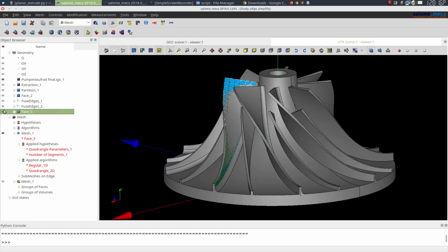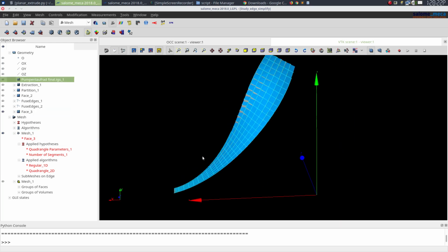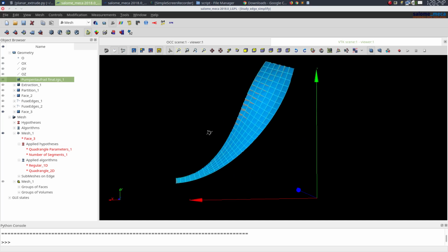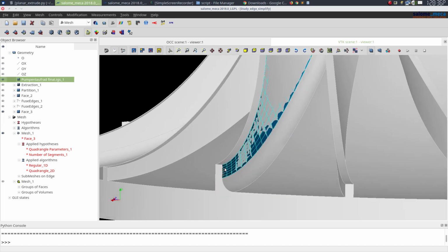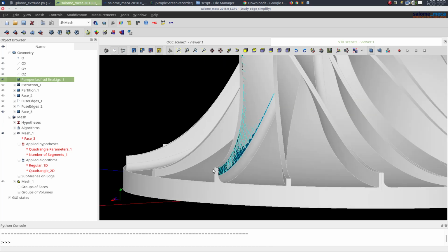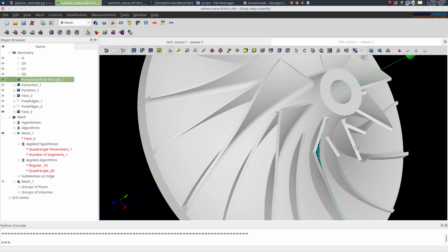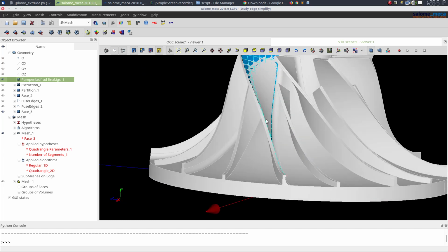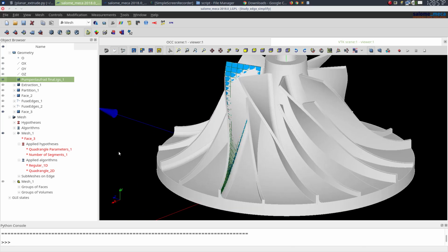and you can easily create this mesh using the quadrangle rules inside of Salome, and we want to offset it to provide a thickness to the impeller surfaces. So you see here we need to cover this thickness, and the thickness all the way around the base surface is constant, so the impeller always has a constant thickness. And again we can use the script, it's very helpful in this case. Let me show you.